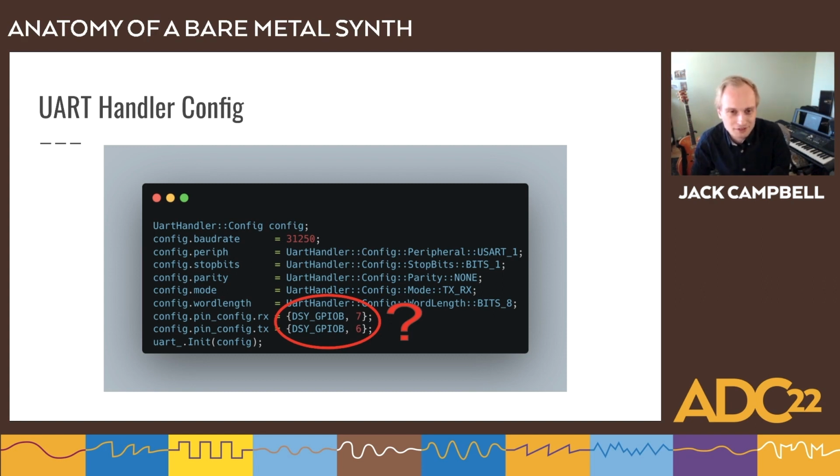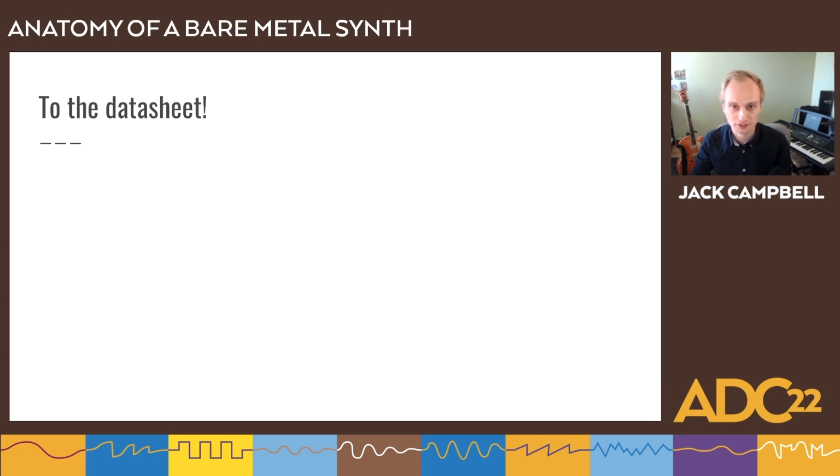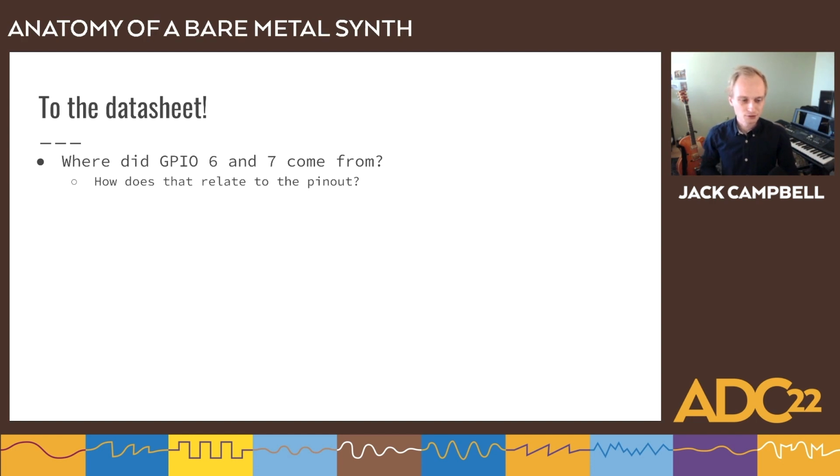Didn't we say earlier, and didn't our pictures have us plugging into pin 15 and everything worked? What's up with that? You can see here, there's multiple numbers, 15, and then there's a 14 there. What's that all about? Turns out pins are actually more confusing than maybe they should be, in all cases. You really need to just know ahead of time that the physical pin will need to be translated depending on how you're using it, whether you're in the code, and even if you're in the code, it can be a different value depending on which library you're using.